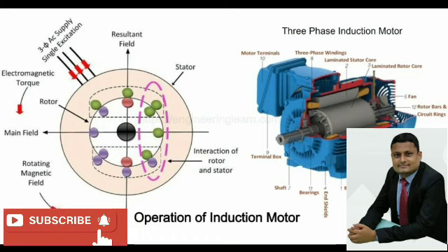Assume average flux density at the air gap to be 0.45 Weber per meter square, ampere conductor per meter 23,000, efficiency 85%, power factor 0.84 and stacking factor 0.9. The motor is to be sold at a competitive price. You have to always keep the cost implication in mind.